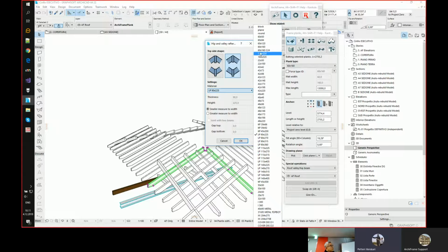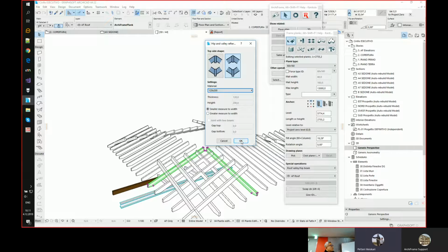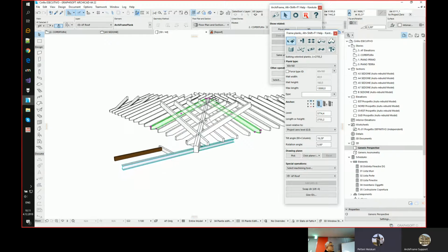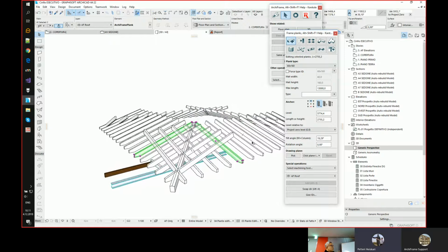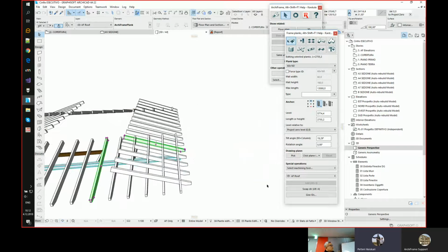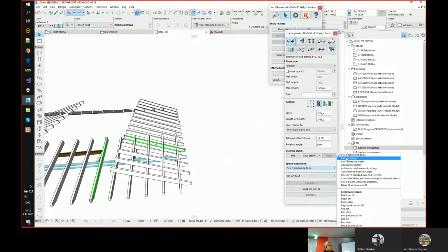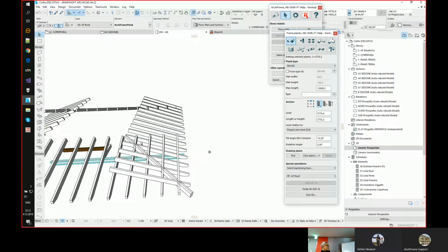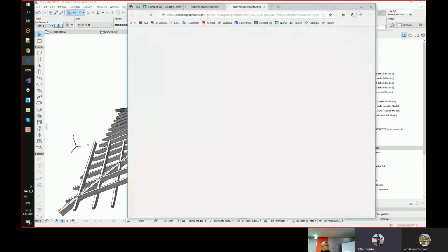The material for this, this was for the rafters. Let's use something a bit bigger for this hip rafter. This 120 times 200 millimeters. Okay, there we have it, the first one. We could mirror this, but let's use this same technique to add it to this other side. So this one, and just okay. And perhaps, oh sorry, I pressed the wrong button.